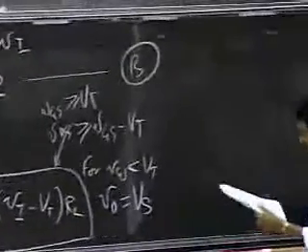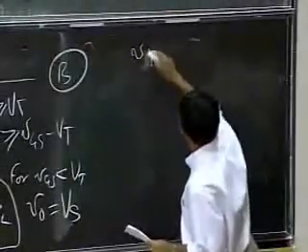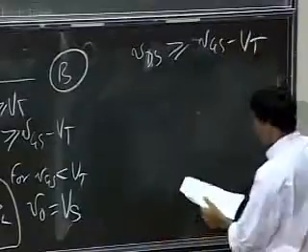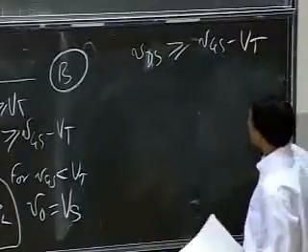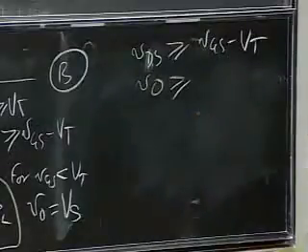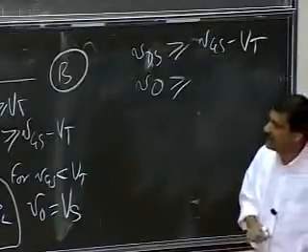I'd like to stare at this constraint with you for a second: VDS greater than or equal to VGS minus VT. And VDS is simply V naught. I want to rewrite this constraint in terms of IDS, because it will come in handy.